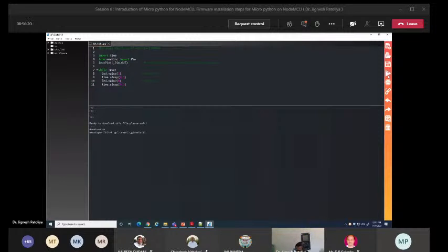So if you reach up to this, it means that everything is fine and you are lucky. Your board is set up, your software is set up, and you don't have a damaged board, you have a fresh one. My tip, or important note, is to click on the stop button before you disconnect your NodeMCU. Now try to understand, it is a real practical. Again I click on this download and run button. This LED is blinking and I click on the stop button. Now I disconnect this NodeMCU from my cable and again I reconnect this NodeMCU.